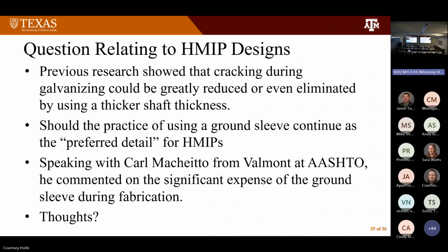Well, that's where we're at. We've got all the data, and we did find, I can't say 31% or something. We're not to that stage yet, but we'll be able to say, of the 120 poles, or of the 40 high mast poles, here's what we found. Of the 40 traffic signal structures, here's what we found. That's our goal, to provide the percentage of cracks. And by the way, it's not that 100% of the poles have cracks, if they're just tiny. It's more about what percentage of the circumference is cracked, what the length and size are.